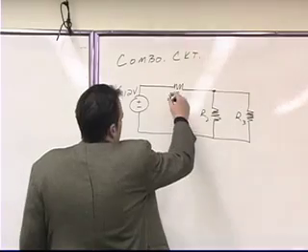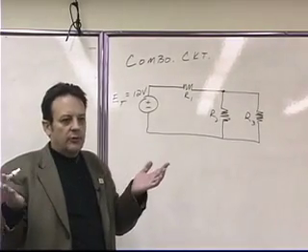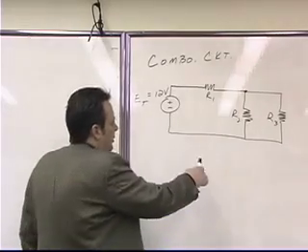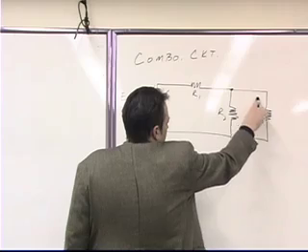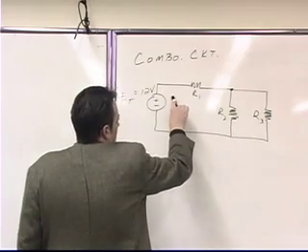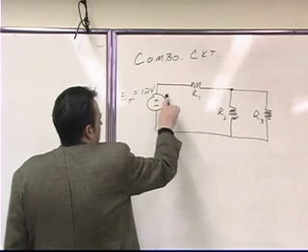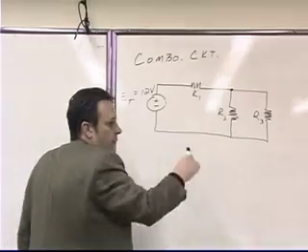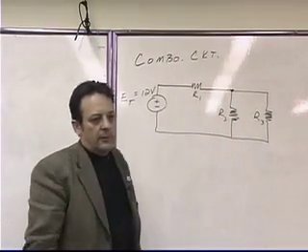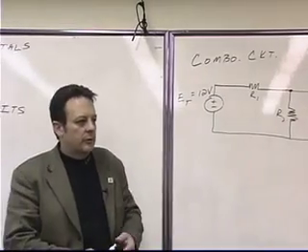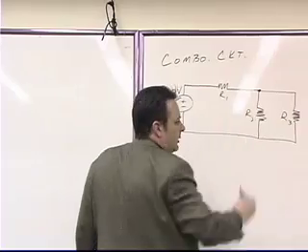Nor can they be in parallel. The reason they can't be in parallel is because, as we've learned in the past, when we have two components that are in parallel, their voltages end up being the same when we go around a closed loop. Like, for instance, if we go around this closed loop, this resistor and this resistor are in parallel because they're the only two components in the closed loop. However, if we go around this closed loop right here, what we find is that we have three components. We have an active component being the battery, and we have two resistors. And so Kirchhoff's voltage law would tell us that the voltage here must be equal to this voltage plus this voltage. Or stated in a more abstract way, the sum of the voltage drops around the closed loop must equal 0. The bottom line here is that resistor 1 is not in series or in parallel with resistor 2.